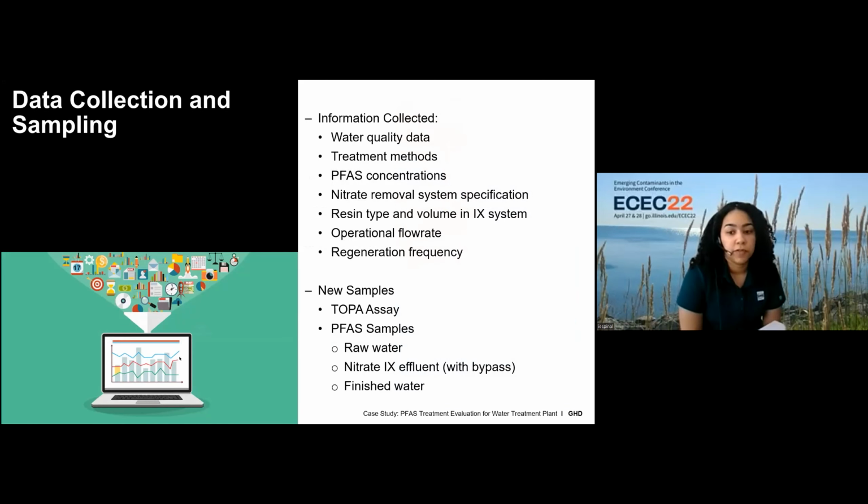So one of the very first steps taken towards PFAS treatment evaluations was to develop a basis of design. To do this, GHD first collected critical information from the client, like the water quality data, the treatment methods, the PFAS concentrations in past years, the nitrate removal system specifications, etc. And we also performed some new PFAS samples at 3 locations within the existing plant: the raw water, the nitrate IX effluent, and the finished water. And we also performed some TOP assay